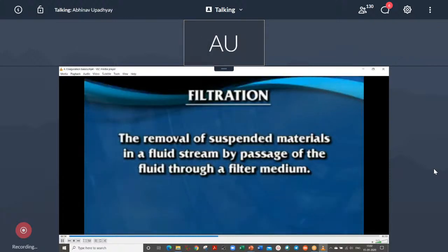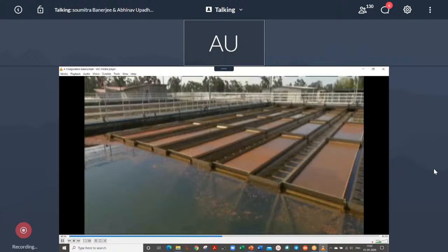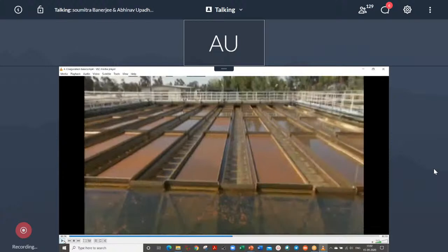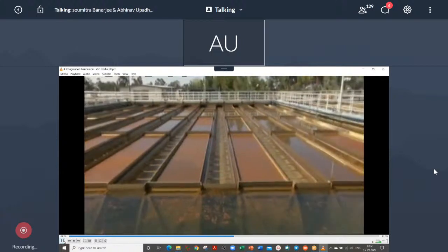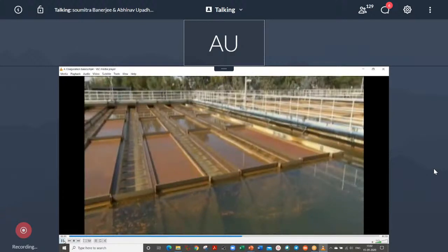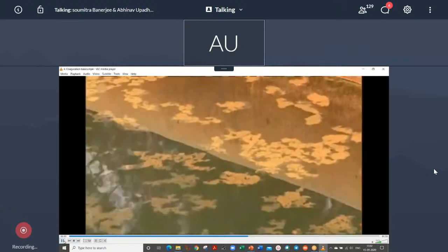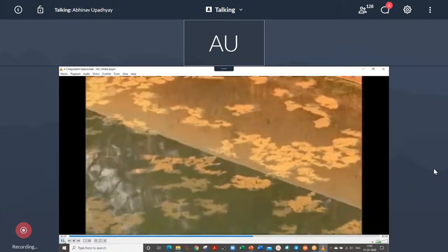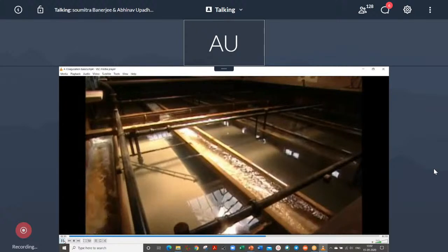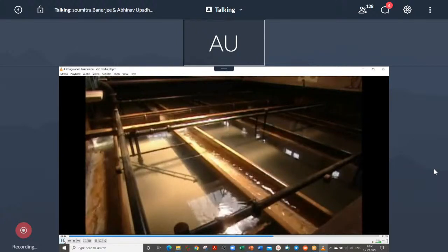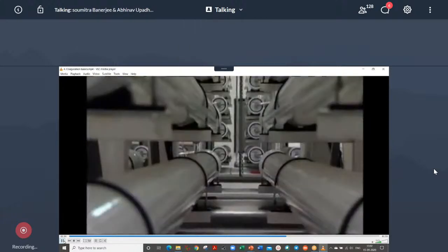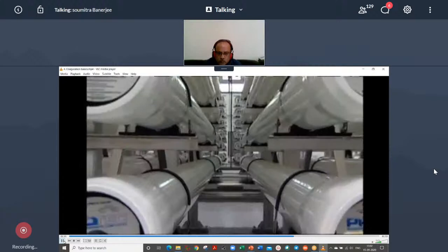And flocculation agglomerate turbidity into larger, heavier particles that can then more easily be removed by sedimentation and clarification before filtration. Filtration is typically accomplished using rapid sand or mixed media filters, but slow sand filters are still in use in some areas. Likewise, newer technologies, including different types of membrane filtration, are also available to utilities.